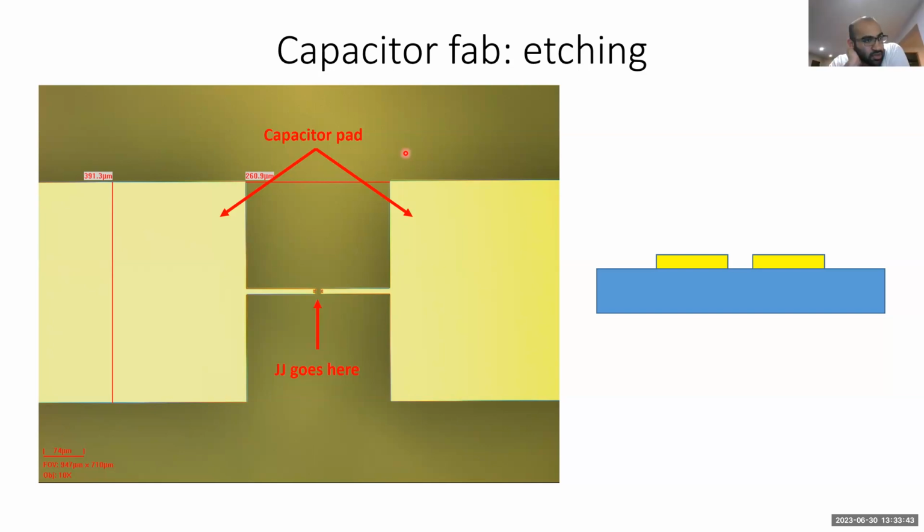I believe niobium and tantalum can actually be etched with chlorine as well. Fluorine is just typically what we like to use. Chlorine-based processes can etch aluminum and its oxides, and sapphire is aluminum oxide.